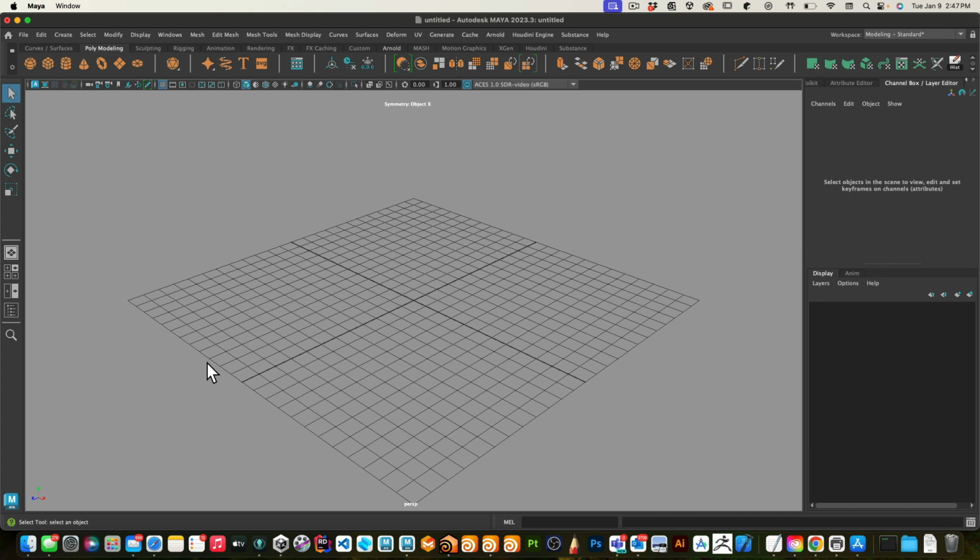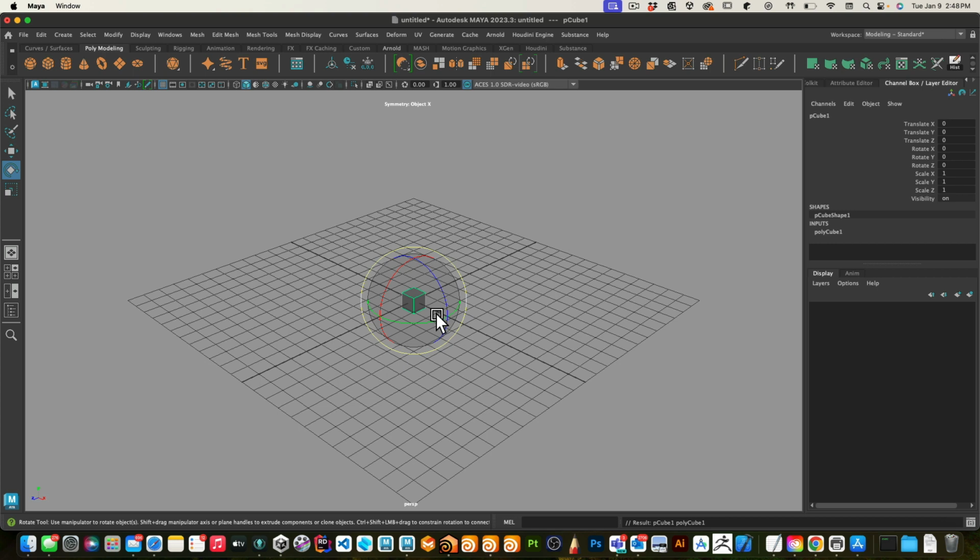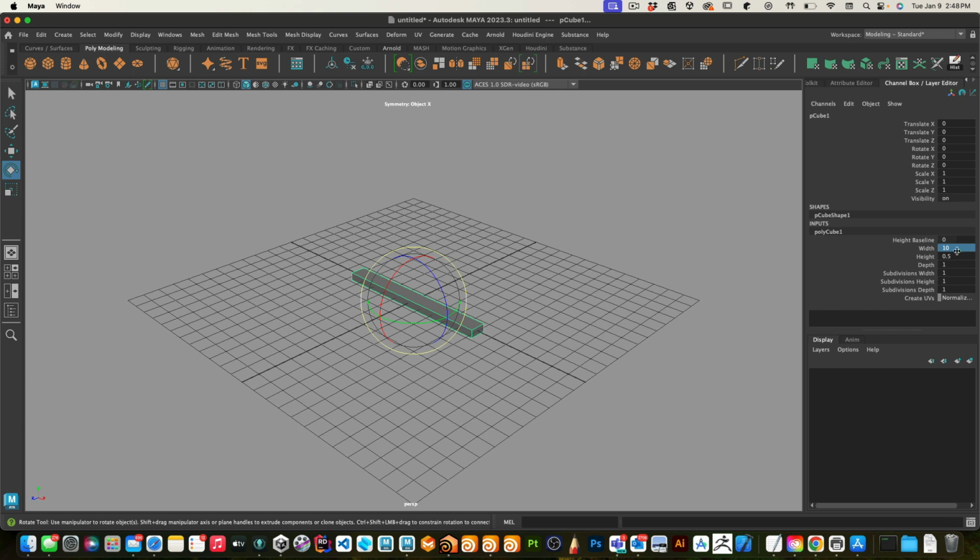Okay, now that's done, I'm just going to give you some thoughts and dimensions on your robot arm with a white box. To do that, I'm simply going to create a box. And rather than scale it, I'm going to go to the polygon here itself and change its height. I'm going to leave it as a 1, maybe a little lower, maybe a 0.5. And then I'm going to give its width. Let's make this width 10, and let's make its depth also a 10.